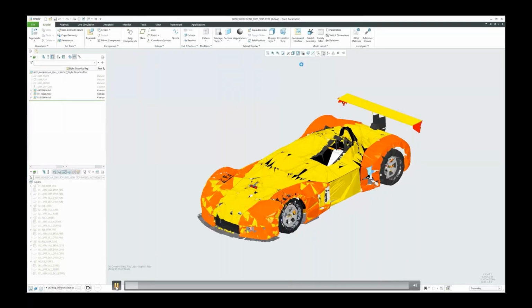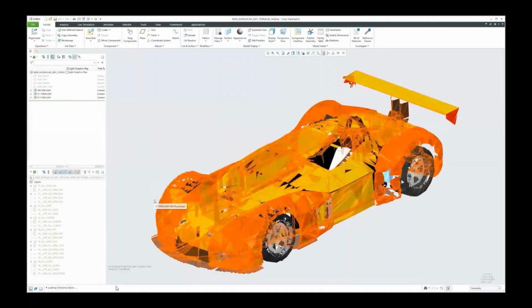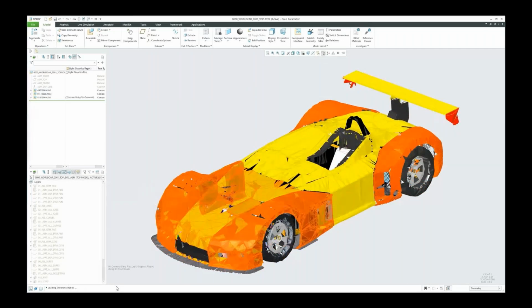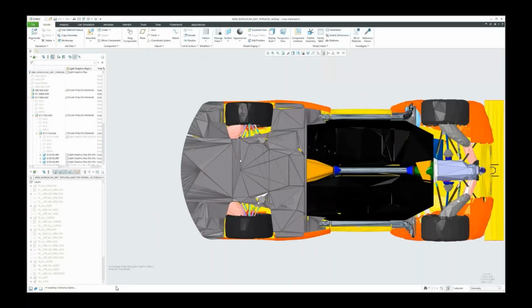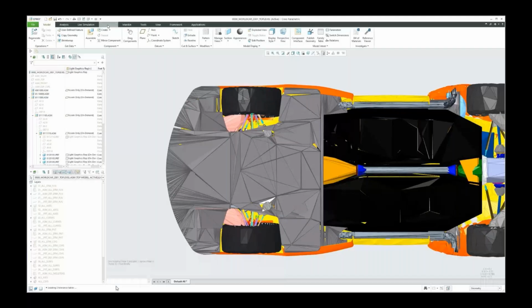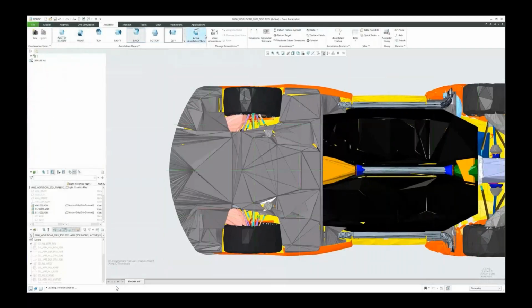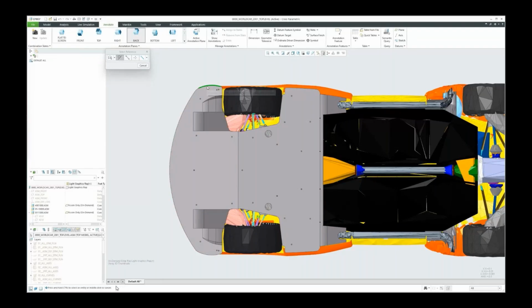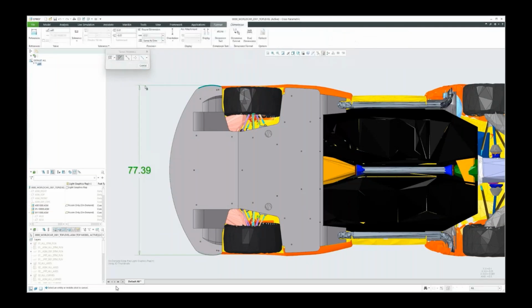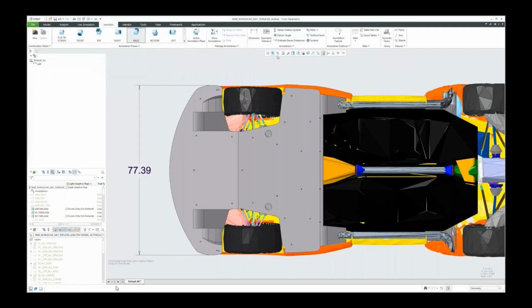So even though it's a bit granular, whenever you click on a component, it's going to drill down to the subassembly, the parts, the further subassembly, those sorts of things, until you get geometry. And then you can start interacting with it. So this is really useful if you want to come in and maybe do some interrogation on the overall design, maybe take some key design dimensions, those sorts of things. So you can work with this data, and it's extremely quick to open. So in here, I can come in and maybe I want to get a dimension on that front splitter. I can drill down till I find geometry that I can actually reference, and I can start making dimensional improvements on it. So real lightweight information loads up in no time, and I can start working on it.